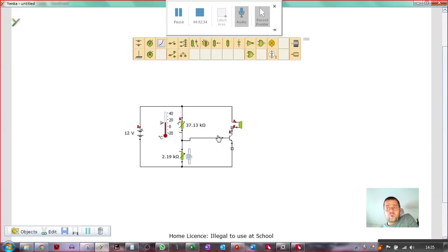The problem with that, and I hope you can see this, is that this is a temperature sensor that's attached to a patient in a hospital. You don't really want to attach a mains temperature sensor to a patient in a hospital. Also, people are going to have to interact with the sensitivity setting on it. You don't want people putting screwdrivers against components that are wired up to the mains. That's really, really dangerous. So we find ourselves in a situation where we really want the input side of the circuit to be low energy, like battery level, 12 volts or whatever, 9 volts, a square battery, whereas we want the output side of the circuit to be really, really high energy.